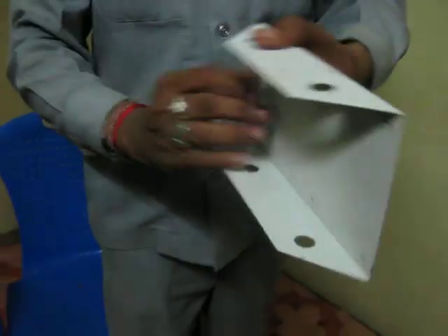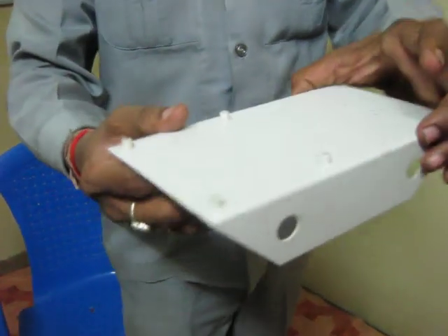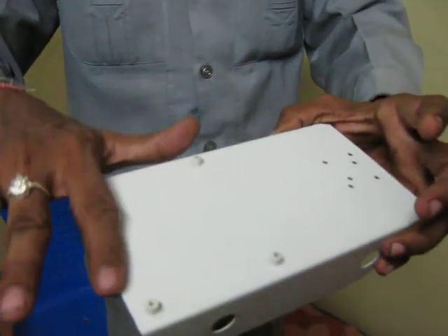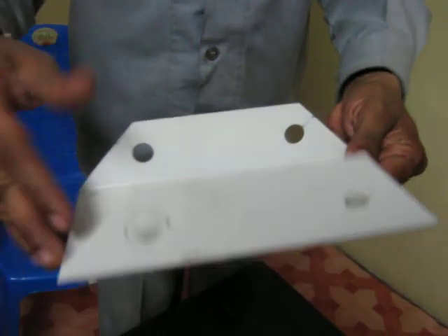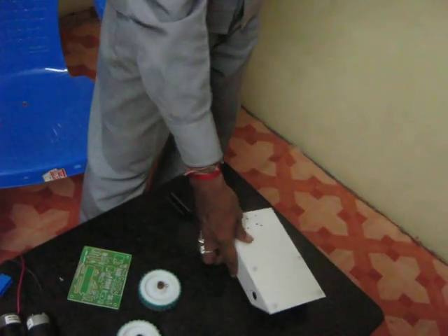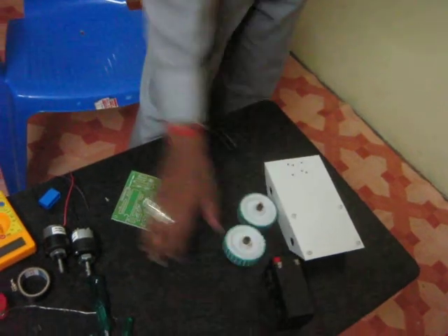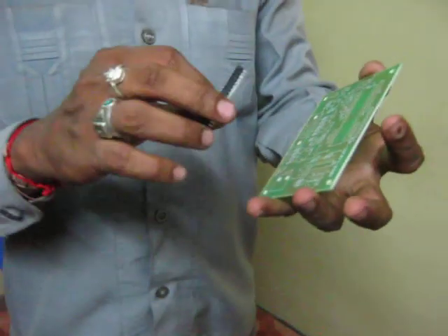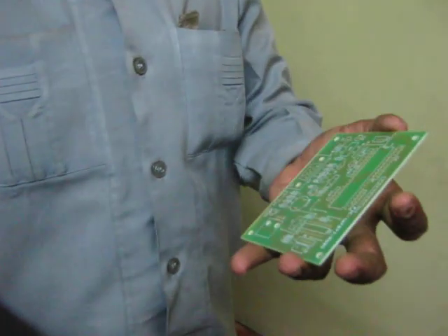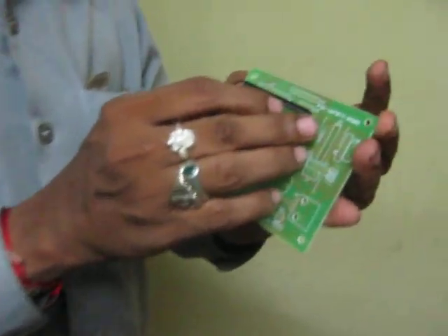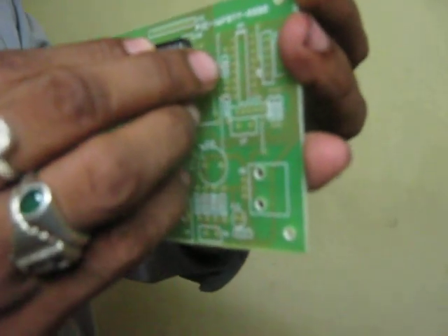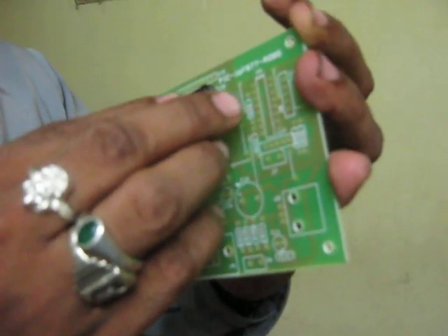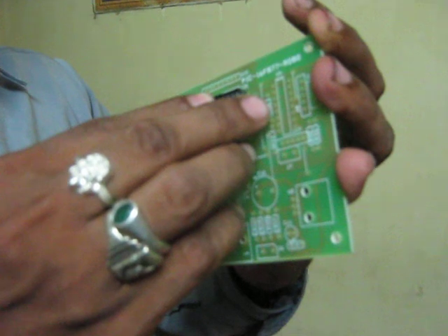This is the robot base. Here you are fixing two motors. Okay, and here we are fixing the microcontroller board. Okay, this is the top of the robot and this is the bottom of your robot. Now we are going to solder this PCB. So here, for inserting the PIC microcontroller, we need a 40 pin base. So you insert this 40 pin base in this PCB. Like that you have to insert carefully. That is very important.